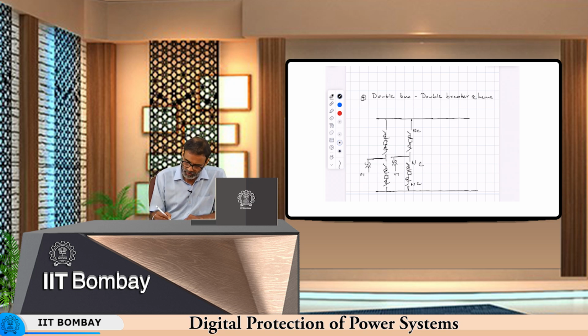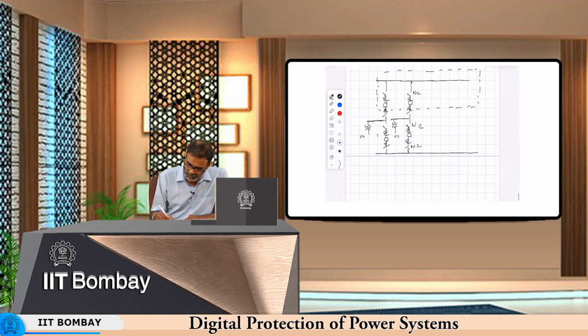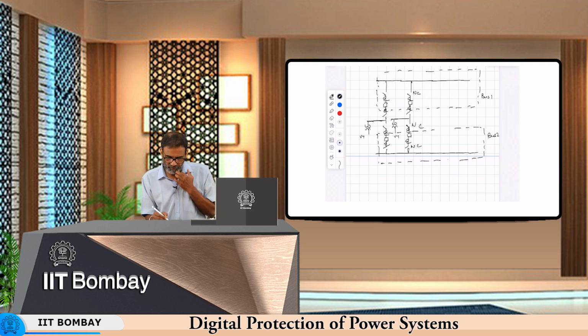And the zone of protection for the bus will be like this. I am of course not drawing all the feeders here, there will be multiple feeders. It is definitely not used in a very small substation. So, this is for bus 1 or main 1, and this is for bus 2 or main 2 differential zone. And for the line, what will have to be done is both these CTs will have to be summated.